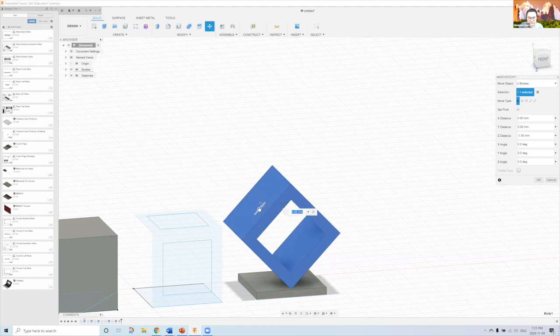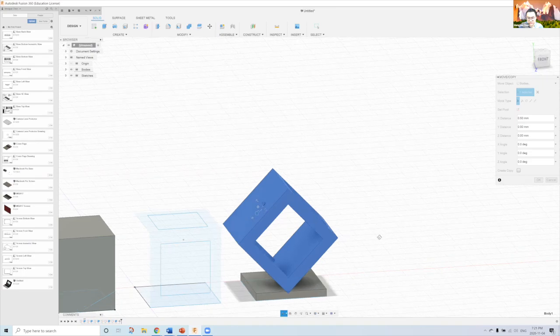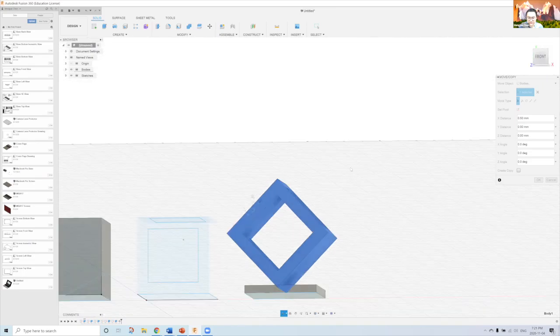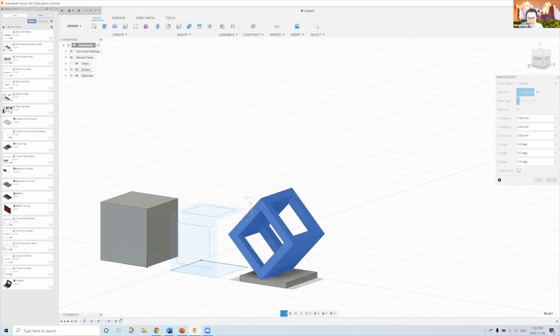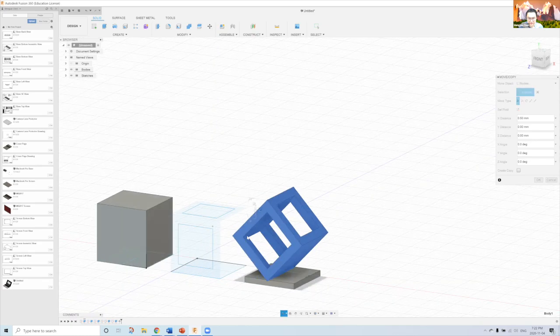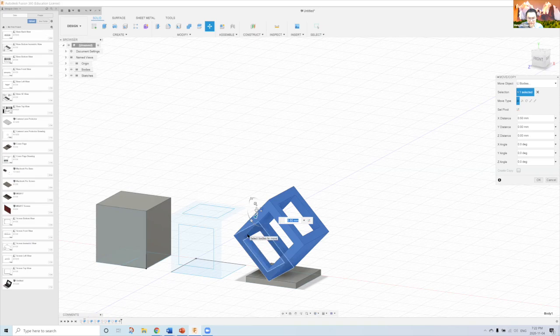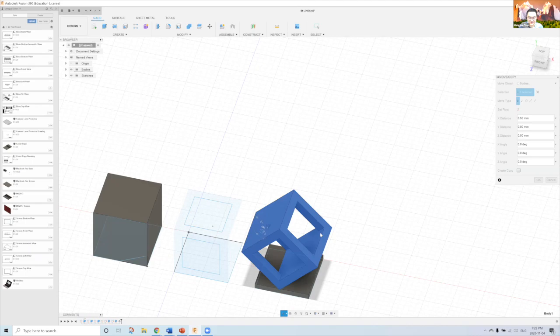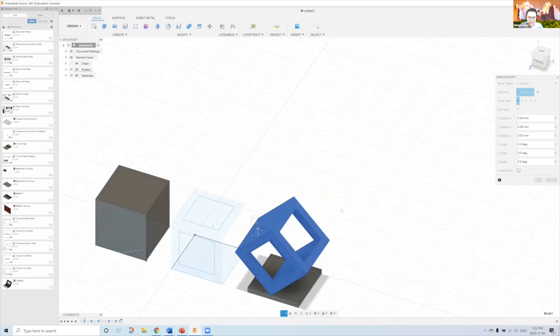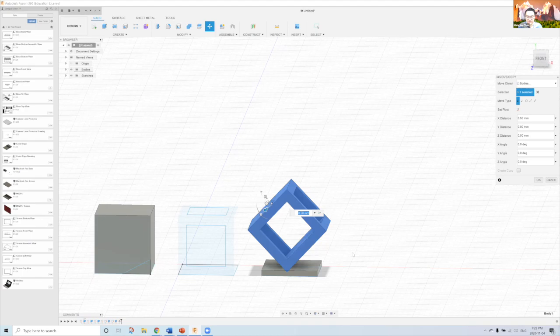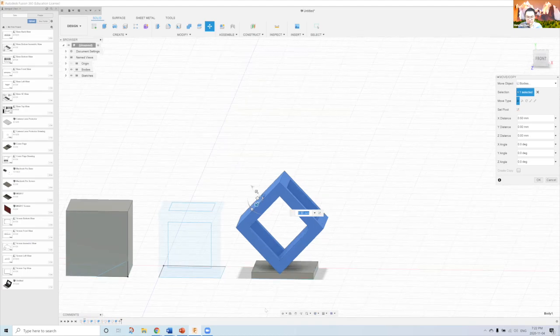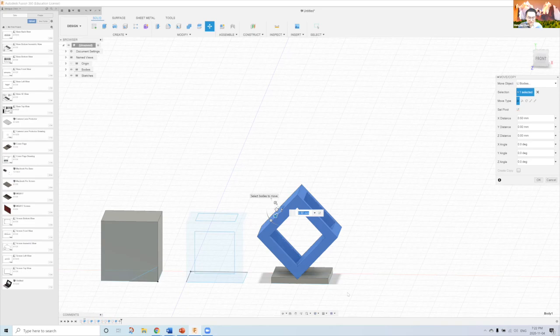And so if you have something like this and you merge the two objects, it actually wouldn't necessarily require supports. What you have is better quality on the side of the print, right? There are no structures more than 45 degrees. Actually, this is not really a good example because you require supports here. But in a sense, when you print in a different orientation like this, you require fewer supports, and the print would come out better in terms of quality.